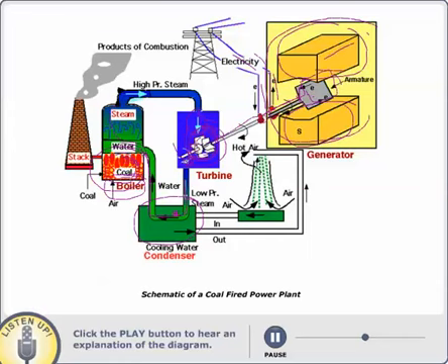And obviously when we turn the steam into water, that energy is coming into this cooling water, and this water turns into warm water, and this warm water is again sent all the way up to this cooling tower. The purpose of this cooling tower is to cool the water that is condensing the steam.